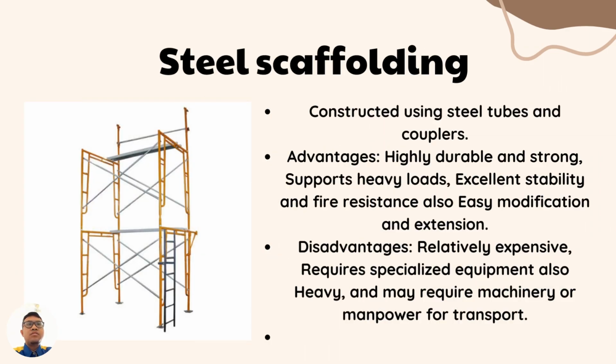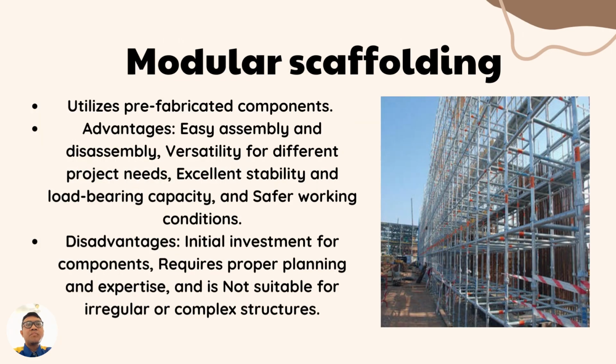It is constructed using steel tubes and couplers. Advantages: highly durable and strong, supports heavy loads, excellent stability and fire resistance, and easy modification and extension. Disadvantages: relatively expensive, requires specialized equipment, also heavy, and may require machinery or manpower for transport.